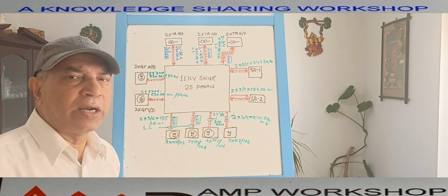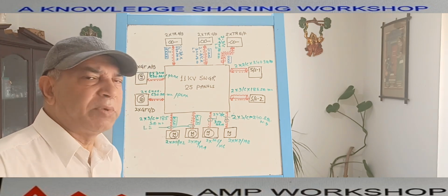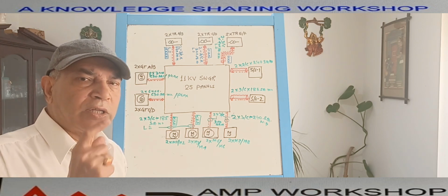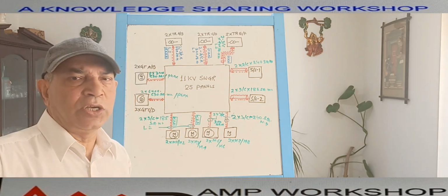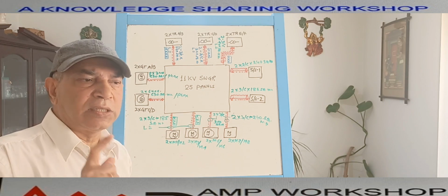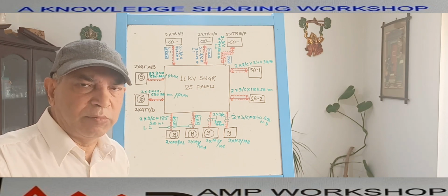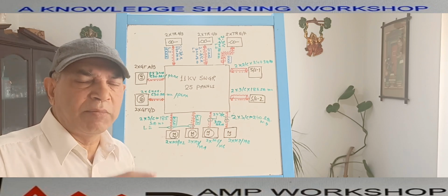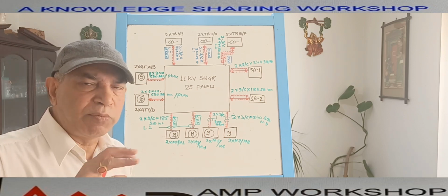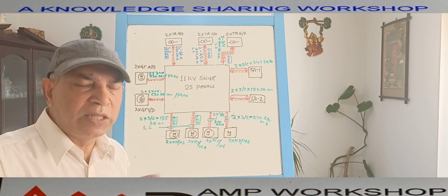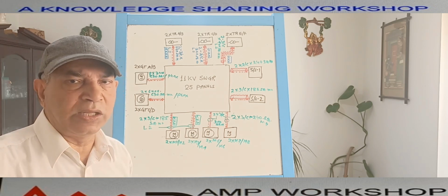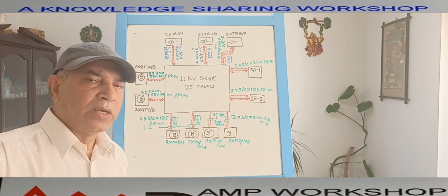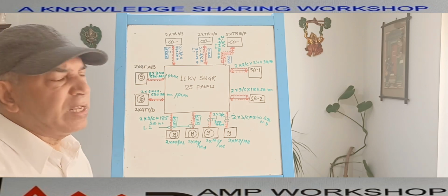the cable block diagram. That's why the cable block diagram is a very important document for the field construction team, so that they can easily decide what mode of laying arrangement, how many cables are coming to the switchgear, what is the entry provision, how much length, what various sizes are there, all this. So that's why the cable block diagram is an important parameter.